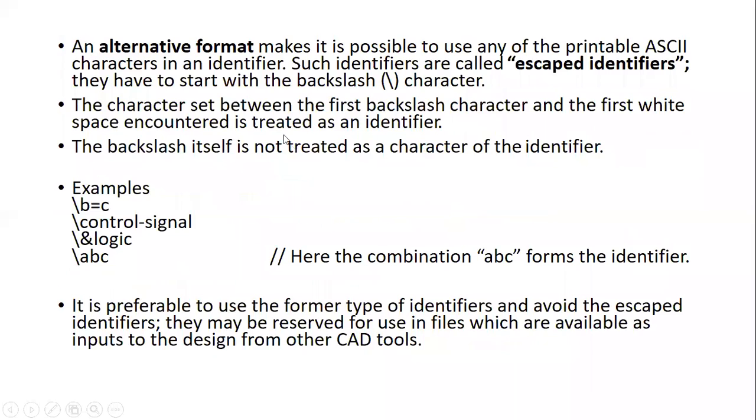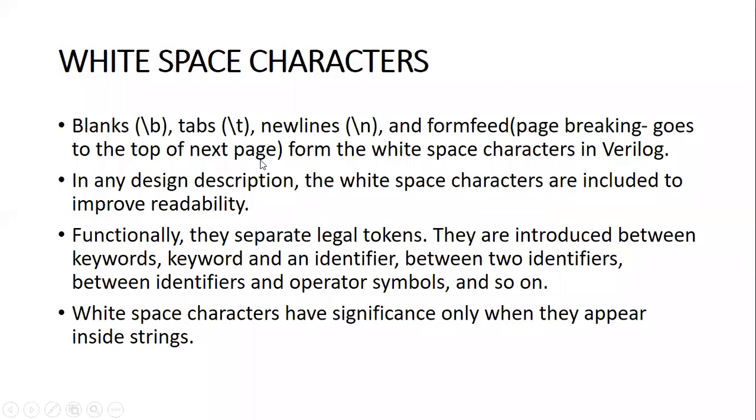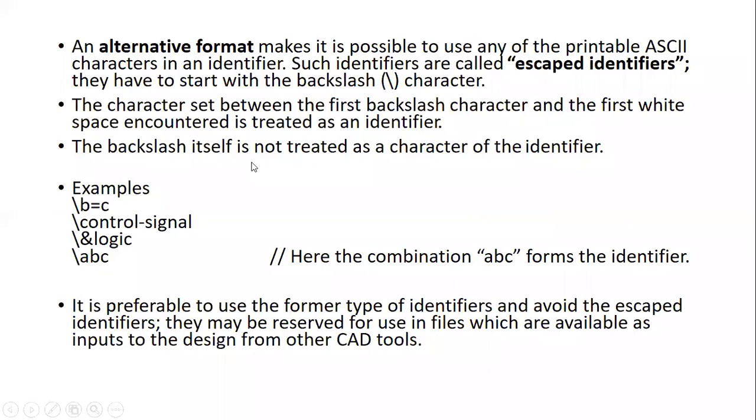There is another method to represent identifiers, that is using alternate format or escaped identifiers. Escaped identifiers always have a first backslash. So what happens when you use a backslash? Let me take the last example. Backslash ABC. So this will be an identifier.